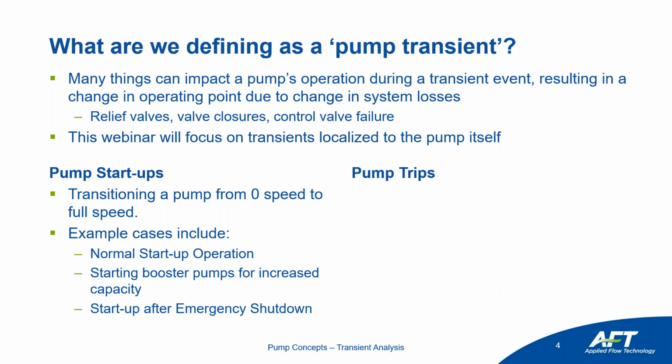Some other cases is starting a booster pump for increased capacity. That could be a booster pump in series. It could be a parallel pumping station where you have variable operating points and you want to increase that capacity. How those different pumps will interact can also be considered in this pump transient analysis.